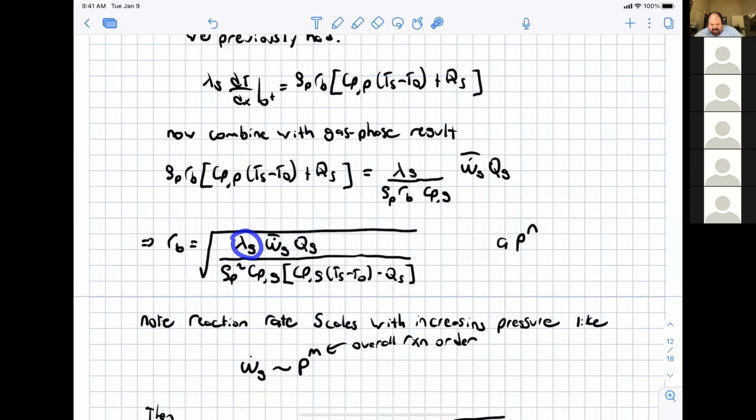The thermal conductivity isn't really a function of pressure. Specific heat of the gas is not a function of pressure, again, unless you start getting to crazy high conditions or close to some sort of critical point. In some propellants, that does become an issue when you're burning them, say for a gun propellant where the pressure can get to 100,000 psi. You do have to worry about that stuff, but nobody ever really accounts for it properly.